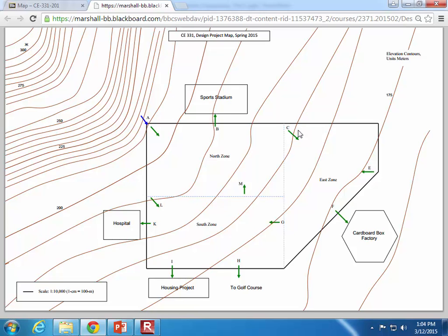cost. But your question was, is it just one pipe per outlet? Once the water gets here, you don't have to have another pipe going somewhere else. There's a junction here, and you specified the demand collection, and that's all you're designing, these main trunk lines. In reality, there will be little secondary lines taking the water from this point to the housing project, for example, but that's not what you're designing. Your design ends at the junction. At least, yeah.